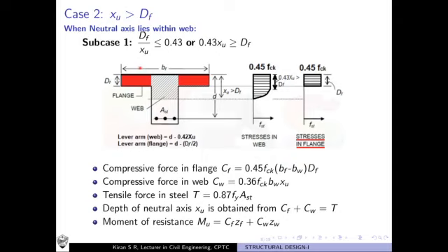It is nothing but, you see here, this entire width is bf, but this width is bw, the width of the web. So it actually represents the effective width of the flange portion, the original flange region, the region shown in red color.